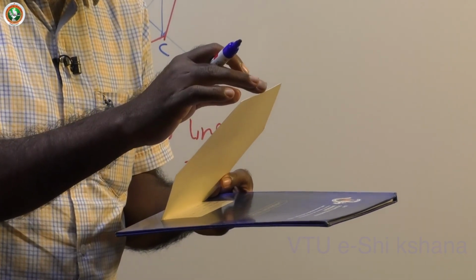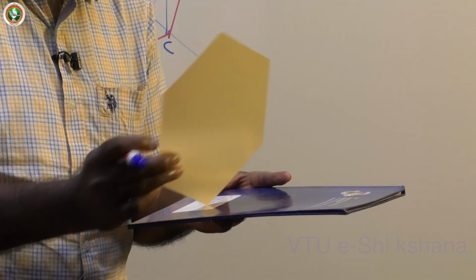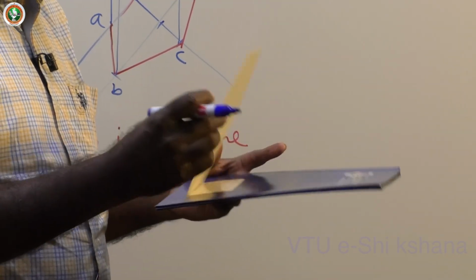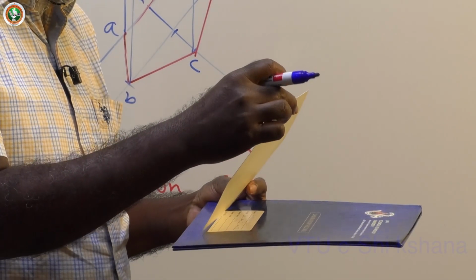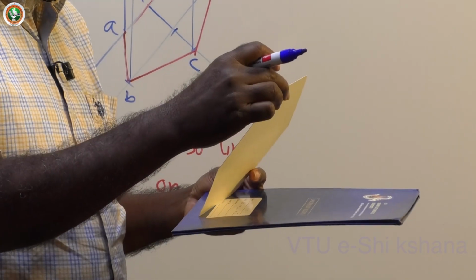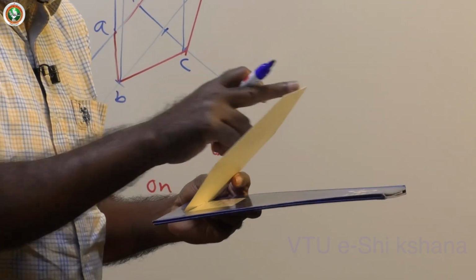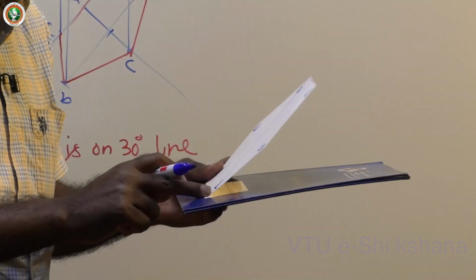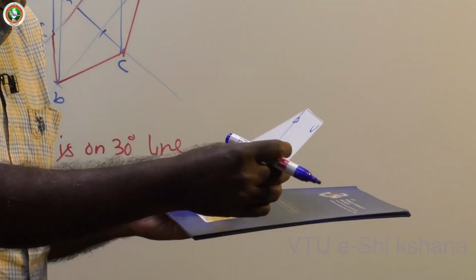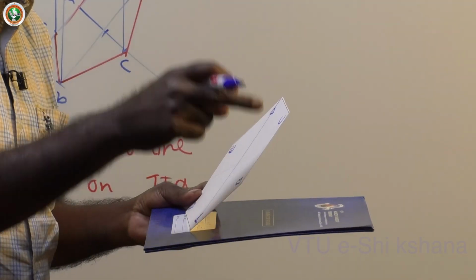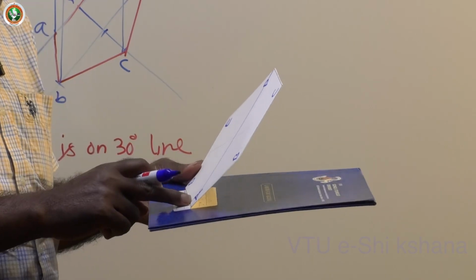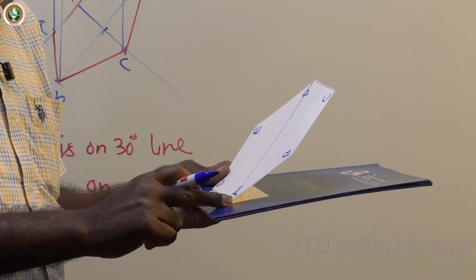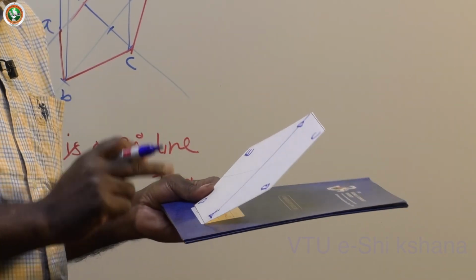The top edge is this. In the case of a corner, I can do anything. The degrees of freedom are many, but here the edge is restricted. We can do only rotation. While doing rotation, I can say this is the problem with a top edge. The top edge is 25 mm above HP, and in the first version he says the side on HP is inclined at some degree to VP. See, this is what I do. Suppose I give it to the top edge only, it works the same. If they give the top edge inclination to VP or the edge on HP to VP, same thing, because these two are parallel.